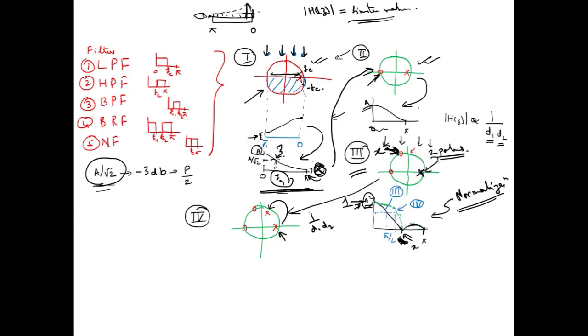And now if you look into the cutoff frequency, previously it was at pi by 2, now it has shifted towards the right. If I bring this pole more nearer, I will be getting a more steeper kind of response.